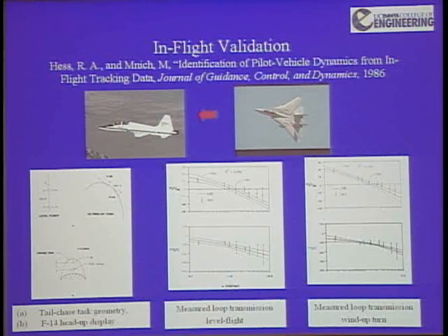What was the task? Well, the F-14 had a little reticle on the head-up display, and it was driven automatically, vertically, by a sum of sine waves that looked random to the pilot. The pilot's job was to keep that reticle on the tailpipes of the T-38.